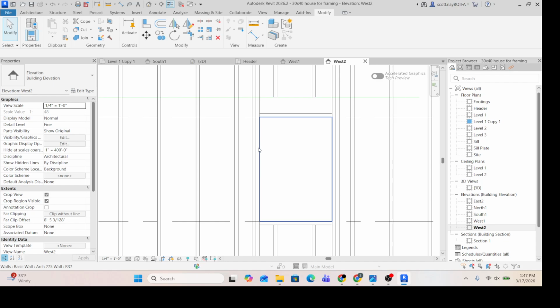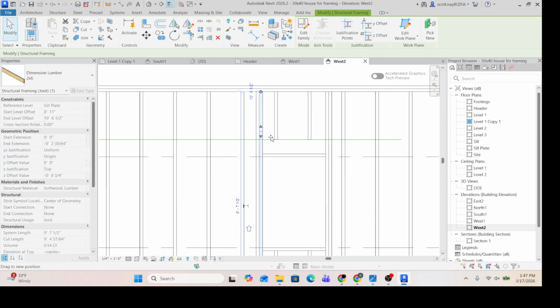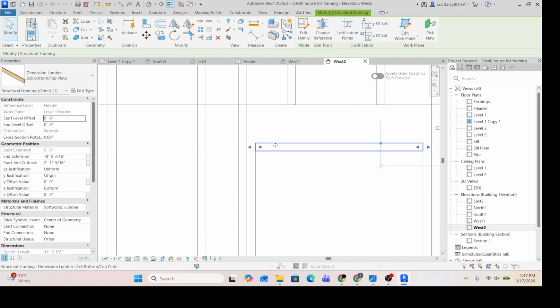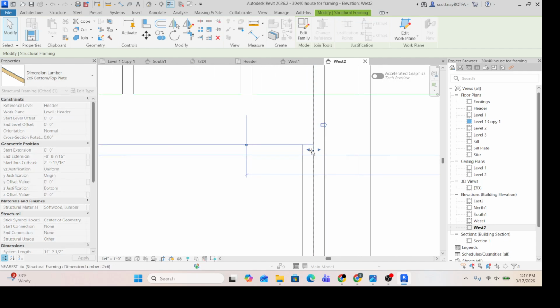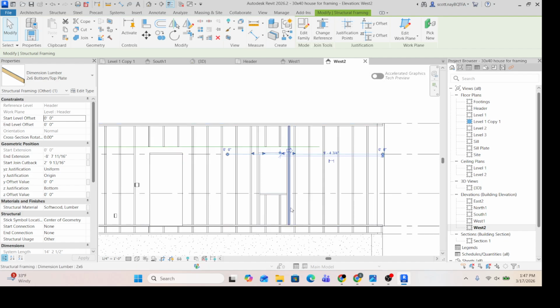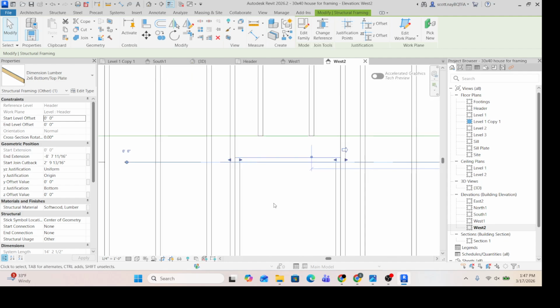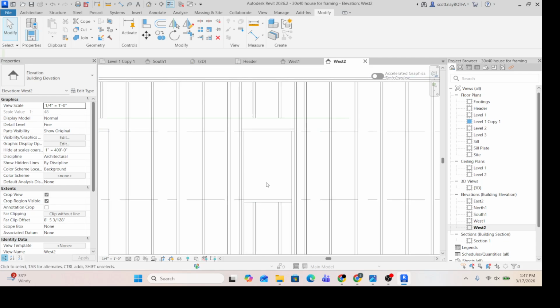So this one right next to the window is sometimes called a trim stud, sometimes a jack stud, and it ends at the same height as the opening. And then this bit here actually extends above it, and so that transfers any loads. So it doesn't end up bowing your window over time. It actually transfers it down the side all the way down like everything else. So we'll have to draw in the 2x8s in a second.